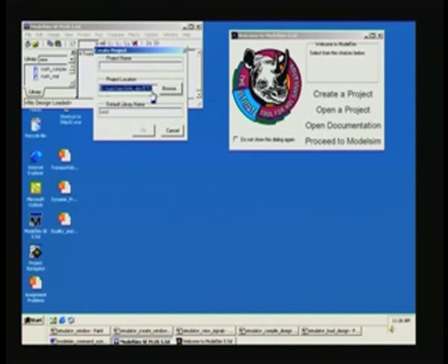You can see this window in a minute, and before that we can key in here. Let us say we want sequential circuits, so we give an apt name there. We will give sequential underscore circuits. So this is the project name that we are going to give, and this is the directory in which all the Verilog files are located for this project.